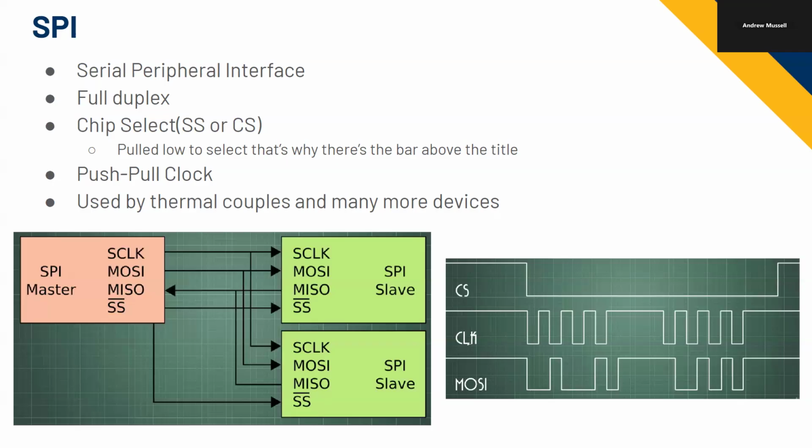Like this, the MOSI and the MISO, are they corresponding ones and then ones leading into the other? So MOSI is when my master wants to send data out and I want the slave to input that data. And then when I want data from the slave to go out and into the master, that's MISO.